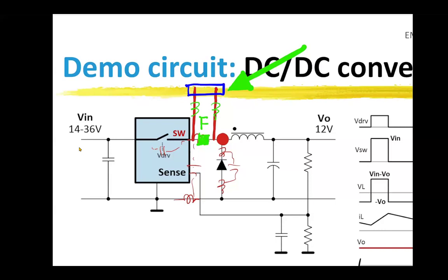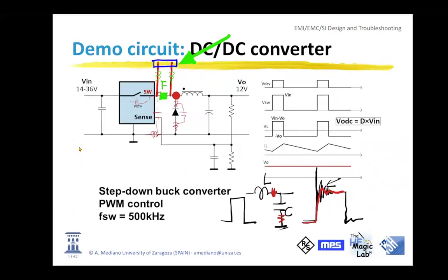No, I insist that you be careful about this technique. And additionally, with this ferrite, we are introducing an inductive effect. The inductive effect at low frequencies can create an increase in emissions, in conducted emissions. If you have the converter switching in this way, perhaps later you will switch in this way. The frequency is lower because you are introducing more inductance, and you can identify an increase in conducted emission below 30 megahertz. Okay.